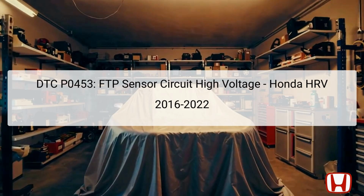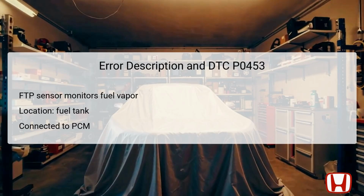The troubleshooting process must begin with the assessment and verification of the system, which is directly impacted by the performance of the FTP sensor and its associated wiring. The FTP sensor serves as a vital part of the vehicle's evap system. Its primary role is to measure the pressure and vapor in the fuel tank, which helps the PCM determine if the emission system is operating correctly.